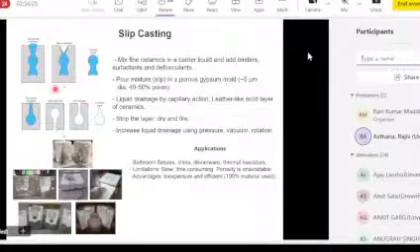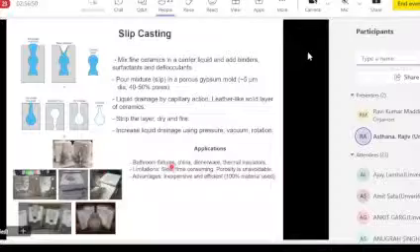You can involve the sintering. If you want to do some surface treatment, like apply a glaze coating or something, you can do that. So very simple process. It's used for relatively simple shapes, things like bathroom china or thermal insulators. It's a slow process, time consuming, but it is quite inexpensive, and you can utilize almost 100% of the material